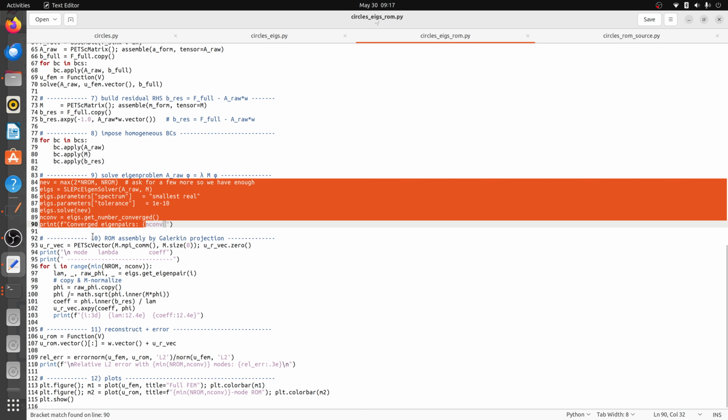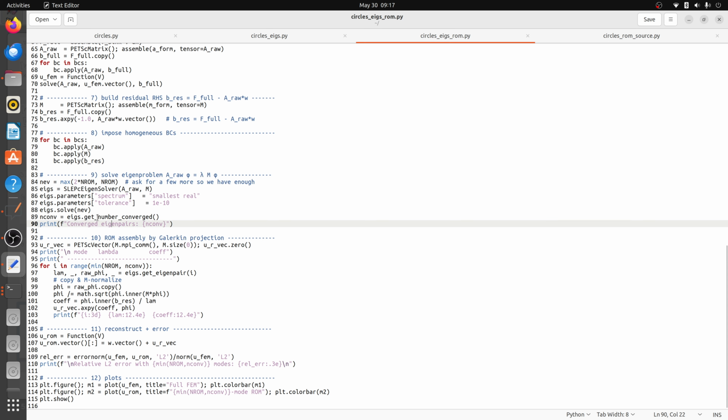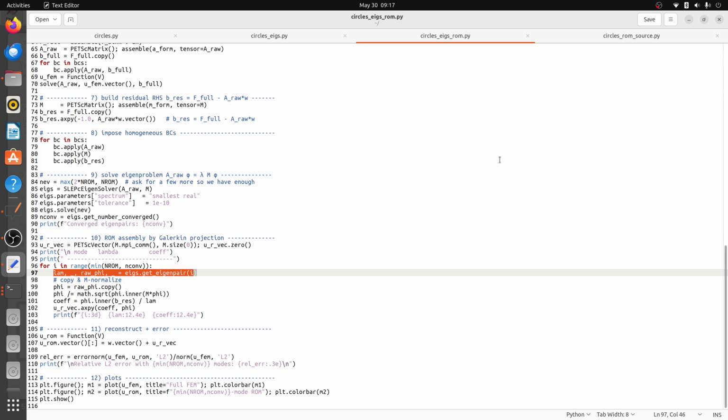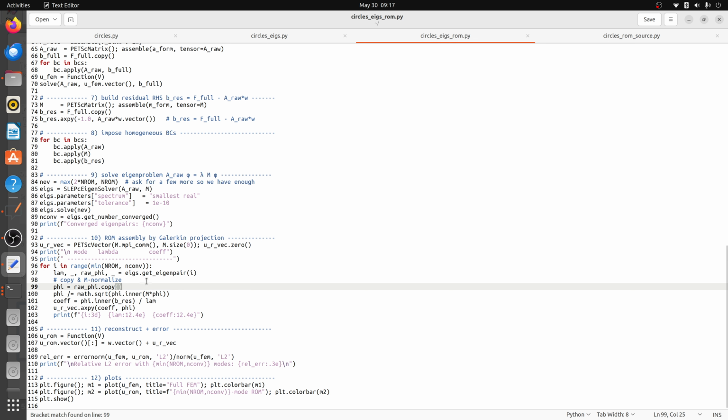And so again the same snippet for your eigenvalue solution, same as before using SLEPc. And now we have got this solution, but we want to extract lambda and phi. So these are the eigenpairs, and here we are running a for loop because we have chosen the number of eigenpairs that we want to extract. So we can run this for, let's say, 5 eigenpairs, right? And we'll extract these lambda and phi values for five of these eigenpairs, right?